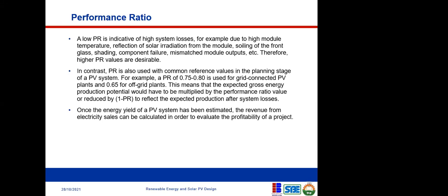You can. These are just assumptions, based on existing projects and tests that have been done on existing projects. Mind you, to determine your real performance ratio, you have to implement a project, monitor that project over a period of time, and then compare the performance with the theoretical capacity of the equipment. But now we are talking about the design stage, because the project is not already existing. To be on the safe side, you should consider this range in your performance ratio.